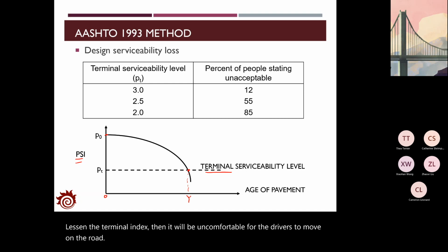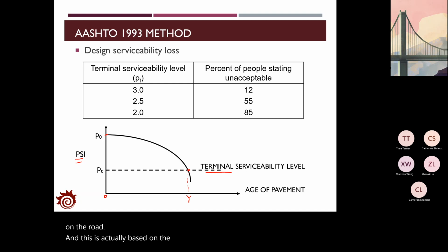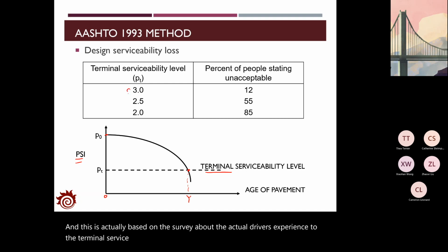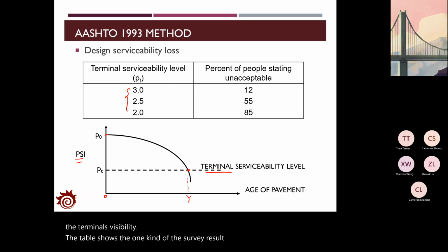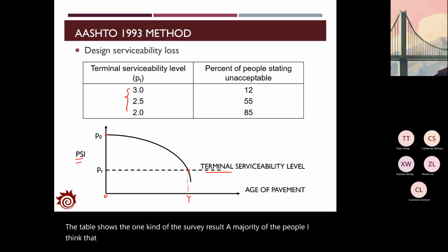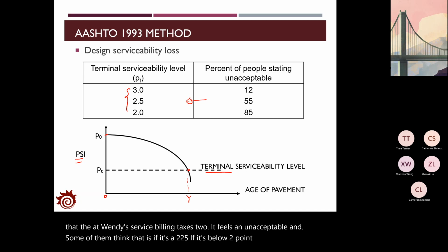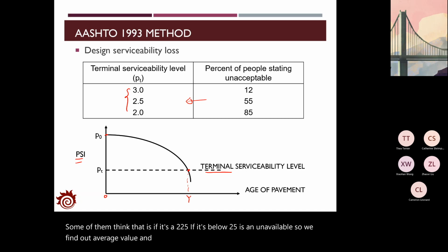And this is actually based on a survey about the actual drivers' experience of the terminal serviceability. The table shows one kind of the survey result. A majority of the people think that when the serviceability index is 2, it feels unacceptable, and some of them think that if it's below 2.5, it is unacceptable. So we find out the average value and determine the terminal serviceability index.